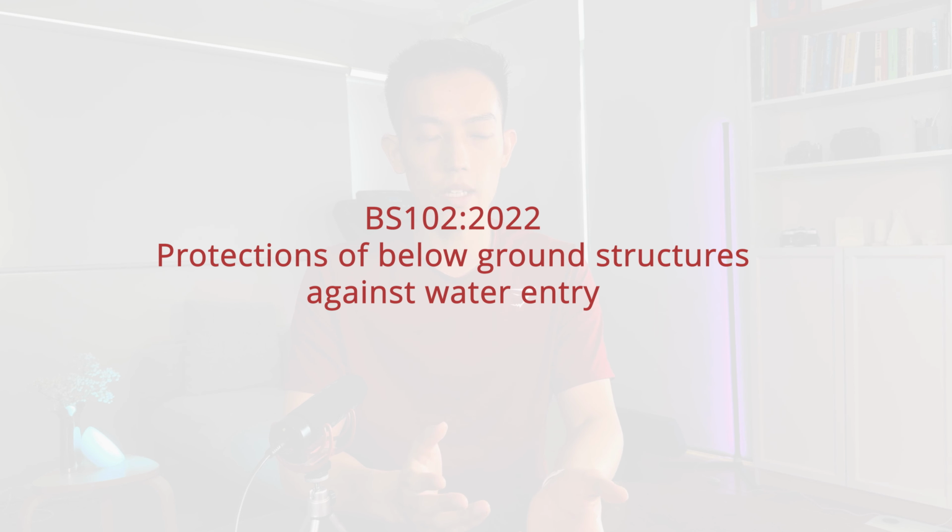There are currently no Australian standards for waterproofing below ground structures. However, there is a British Code of Practice, BS 8102:2022, Protection of Below Ground Structures Against Water Entry. While it is a very comprehensive document, it may be tough to navigate and apply. Hence, in the water shedding online courses that I took, Ross Taylor, industry leading expert, suggests these 3 rules of thumb.